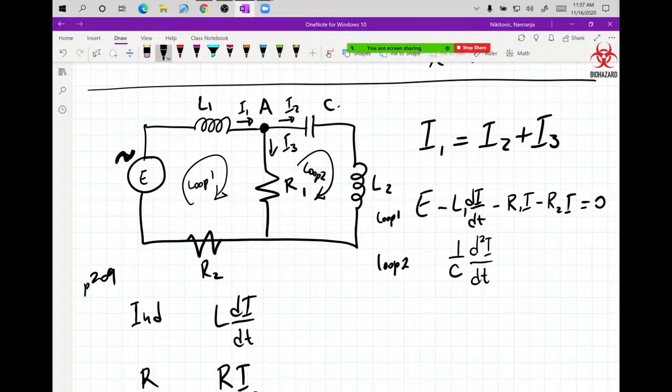So C2 with a capacitor, okay, so that's spending, and then L2 is spending, so it's going to be plus L2 di/dt, and then I2, now the loop goes this way, and it's going opposite to the current, where before it was going with the current, so now it's going to be a minus of R1 I3, and all of these guys are I2s. Because remember, we have 3 currents that are equal to 0.